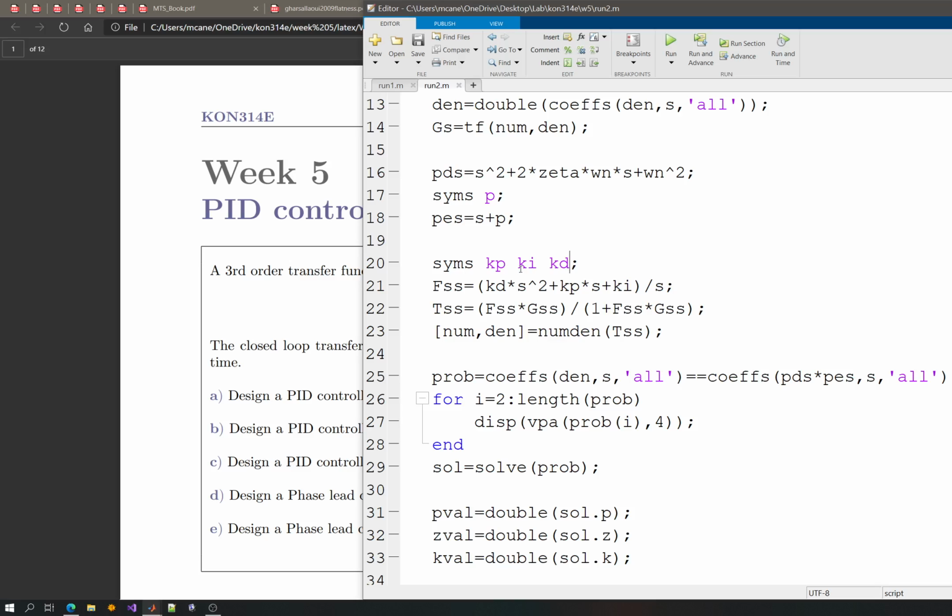The closed loop was the same as the open loop. So I had the same degree. Here I'm not canceling anything, I'm adding 2 zeros and 1 pole. As in the case in the PID controller design, I am basically adding a pole to the system. The amount of zeros doesn't affect the degree of the system for now. Basically, I will have a fourth order system.